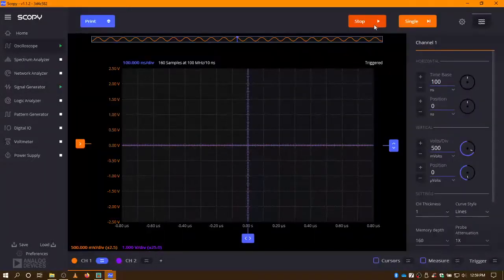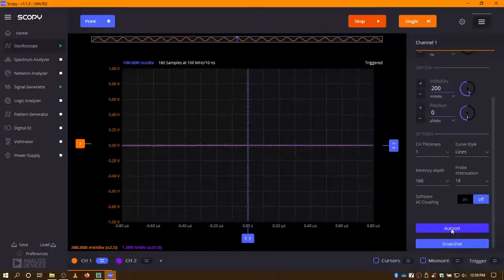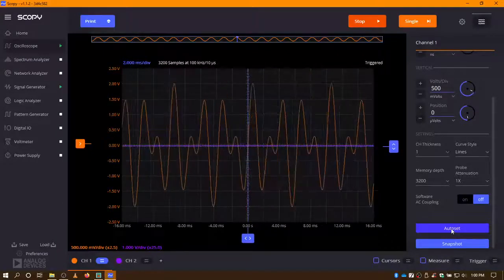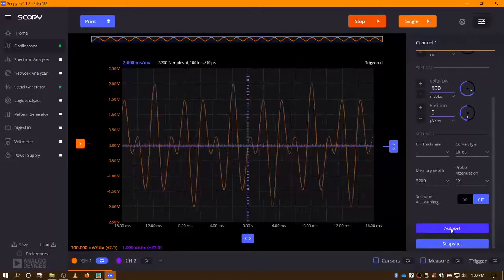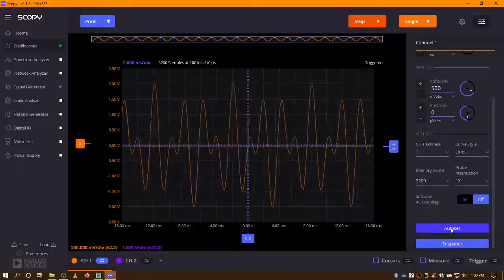I'm going to go over here to the oscilloscope, and I'm going to make some adjustments. Actually, I'll try something called the auto set feature and see what that does for us. There. Auto set is an attempt at auto scaling. It'll work some of the times and not all of the times. Usually when it's a very small signal, it won't work.